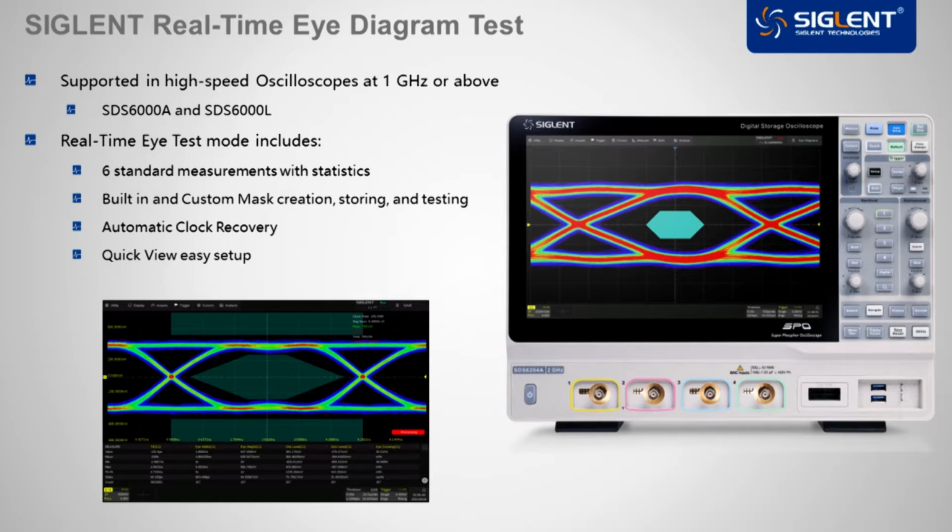Here today to talk about our measurement capability for real-time eye diagrams. This option is supported in our high-speed oscilloscopes at or above a gigahertz, including the SDS6000A and 6000L series. The real-time eye mode itself includes 6 standard measurements, including interval error, eye height and width, the 1 and 0 levels, as well as an eye crossing.